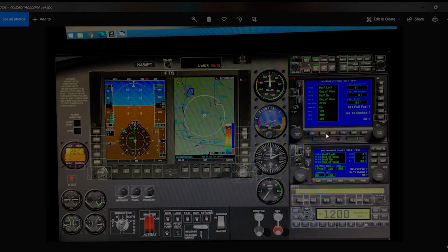The OBS mode over here will be for setting GPS purposes. If you set a fix somewhere and you want to track to it a certain way, like on your own from a certain radial, or say an airport, select the direct to an airport or an airport that you're already tracking towards via your flight plan.